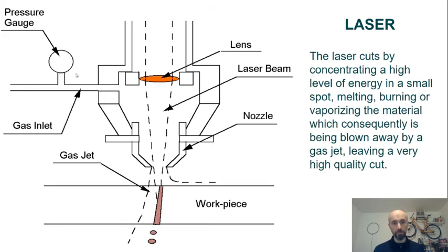In the most cheap laser cutters, typical machines from Fab Labs, it is just compressed air. This flow of air keeps the lens clean, so it blows away the smoke. This is very important because the lens is transparent, but the smoke is not. So if the lens gets stained, the laser will actually cut the lens instead of the piece you want to.